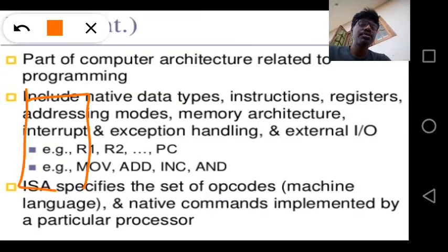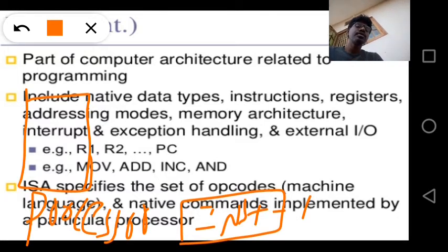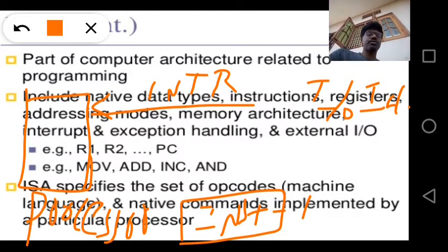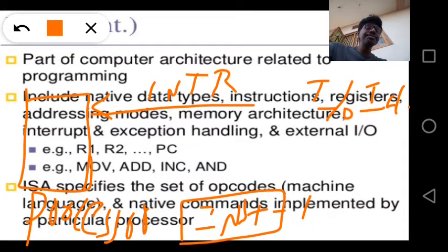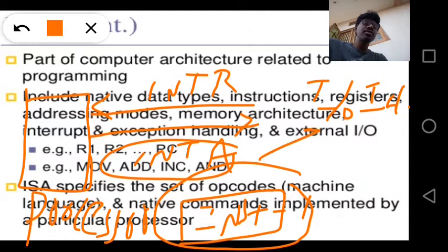If this is my processor, when it is executing instruction 1, and it receives an interrupt request signal from some IO interface, it will complete the execution of the current instruction, and then send an interrupt acknowledgement signal to the IO device.